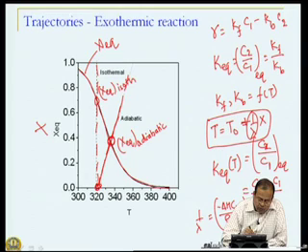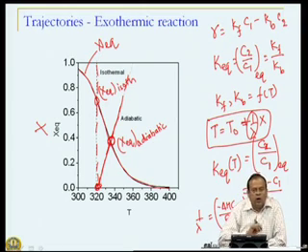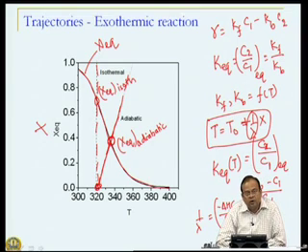Now, kinetics, if you see, temperature is constant. So, in general the rate of reaction will be low. Here the temperature is increasing if you are travelling along the adiabatic path, that means the reaction rate is now increasing. So, we will reach the equilibrium conditions much faster compared to isothermal. So, the kinetics is favorable on an adiabatic path, but the thermodynamics is not, whereas in an isothermal reactor operation kinetics is unfavorable, whereas the thermodynamics or equilibrium is favorable.